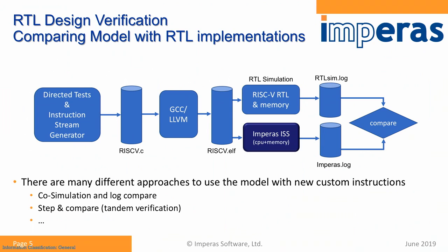And the last slide is we're also doing verification. We have a demonstration of this also on the open hardware stand where we're running our reference simulator against RTL. It's actually a RISC-V core in there, and it uses a random instruction stream generator, open source stream generator in there, so you can get verification of your design. Thank you very much.